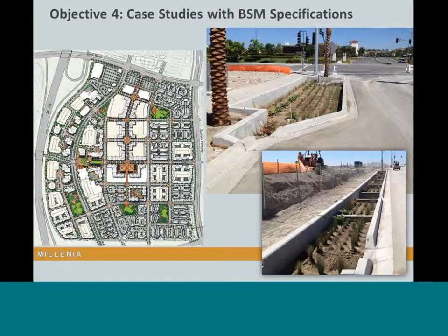And then where you didn't have parallel parking, a linear facility was installed in this location. So due to the urban density and the large buildings, this is where you ended up with vertical cutoff walls. So a little more expensive, and if you've got a little more space and right-of-way, then you can avoid the cutoff walls like this and actually have your natural side slopes.